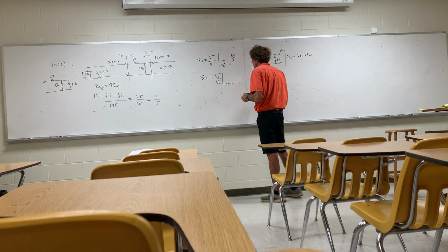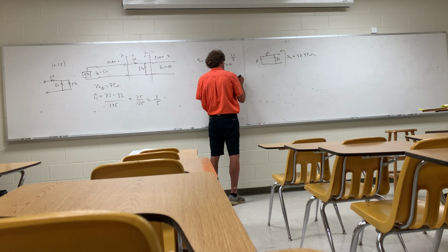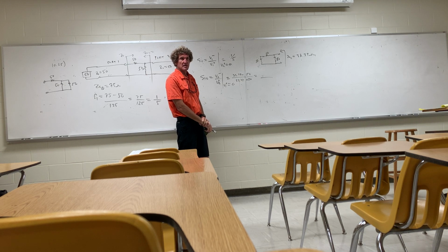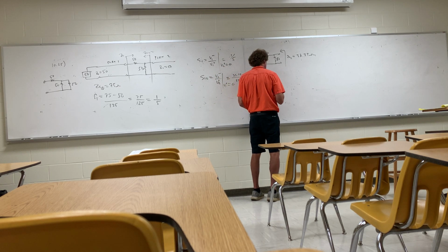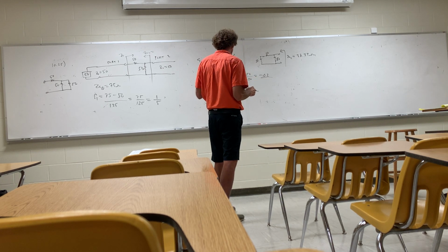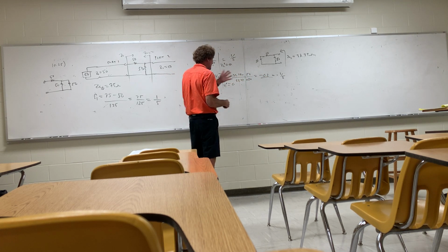So now we come down here, and again, that first port's matched. So that's the impedance I'm going into, 33.33 minus the impedance I came from, which is 50, over the sum of the two, 33.33 plus 50. Well, what's that going to be? It's negative, isn't it? Correct, class? 33 minus 50 has got a negative on it. What do you get? Minus 0.2, or really minus 1/5.